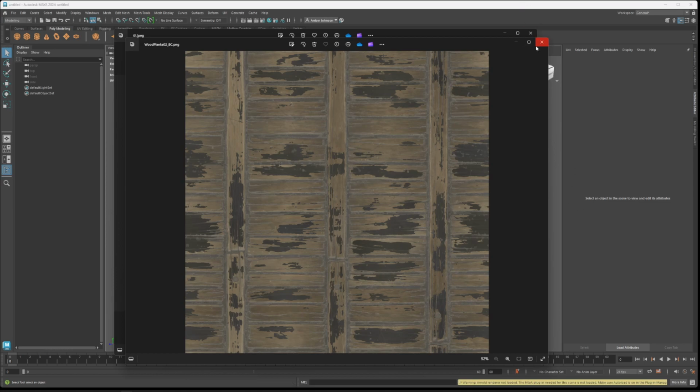So how do we actually work with these? I kind of alluded to it earlier that you almost have to work backwards. You have to be very thoughtful of what you're doing. You can't just open up Maya and model out some stuff and then go to Substance Painter and start applying materials, because tileable textures do not work correctly in Substance Painter.